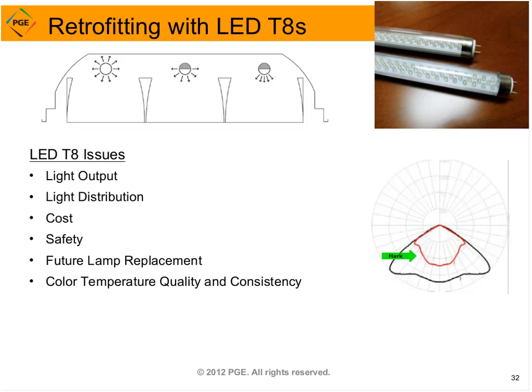All fluorescent lamps that are rated for a certain color temperature look pretty much alike. LED T8s, though, may have inconsistent color, and that can shift over time. So this is important whenever lamps of any kind are close together, as they are in a parabolic fixture with exposed lamps. Now, I'll grant you that T8 lamps with different color temperatures get stuck in fluorescent fixtures all the time. So that can be an issue there as well.